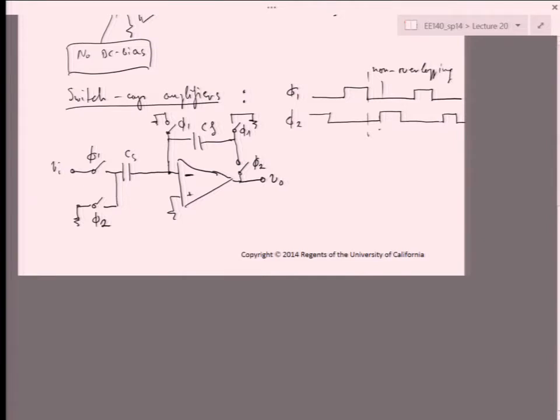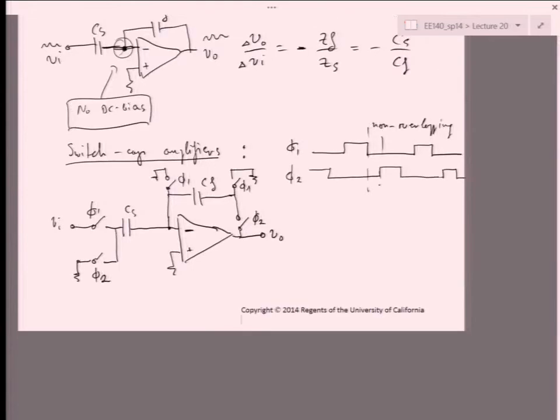So there's no way that at any given point of time both switches, Phi1 and Phi2, will be on, and so short circuit currents can go through, right? Because of the non-overlap, I'm directing the charge to charge the capacitors the way I want. So there's no stray paths for charge to escape this system.